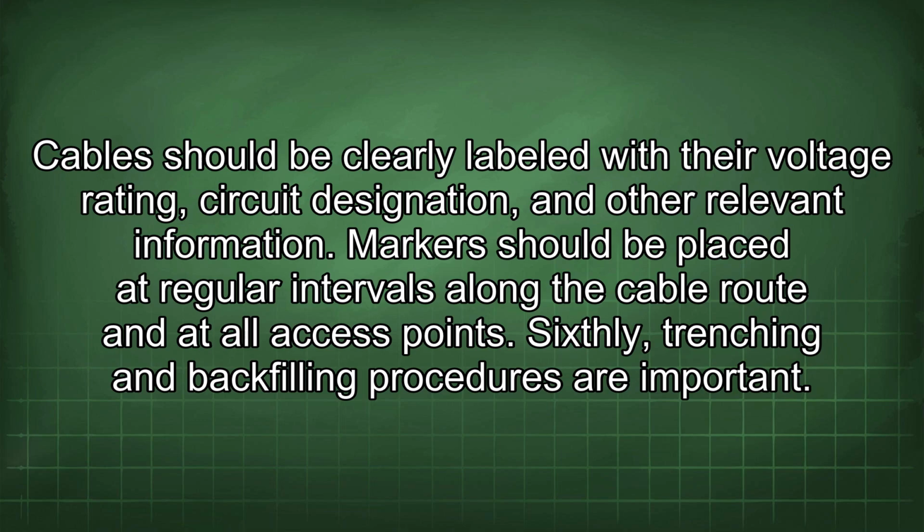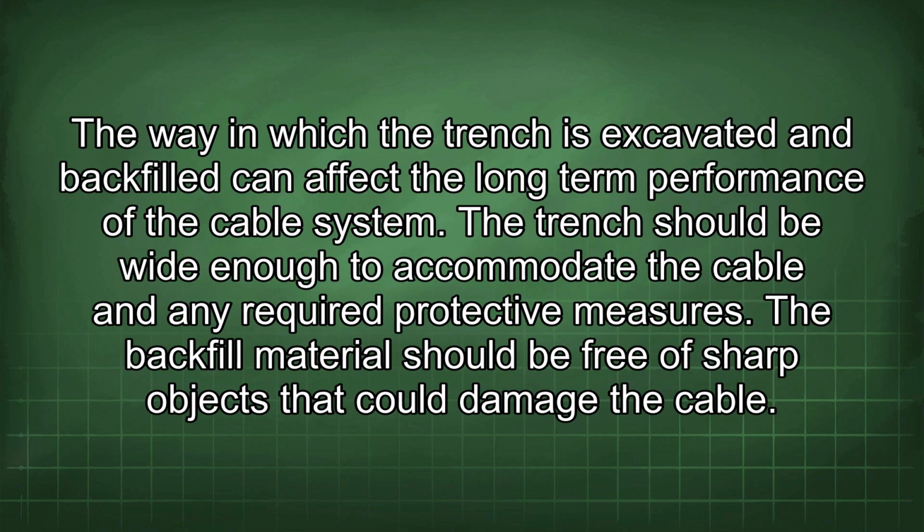Sixthly, trenching and backfilling procedures are important. The way in which the trench is excavated and backfilled can affect the long-term performance of the cable system. The trench should be wide enough to accommodate the cable and any required protective measures. The backfill material should be free of sharp objects that could damage the cable.